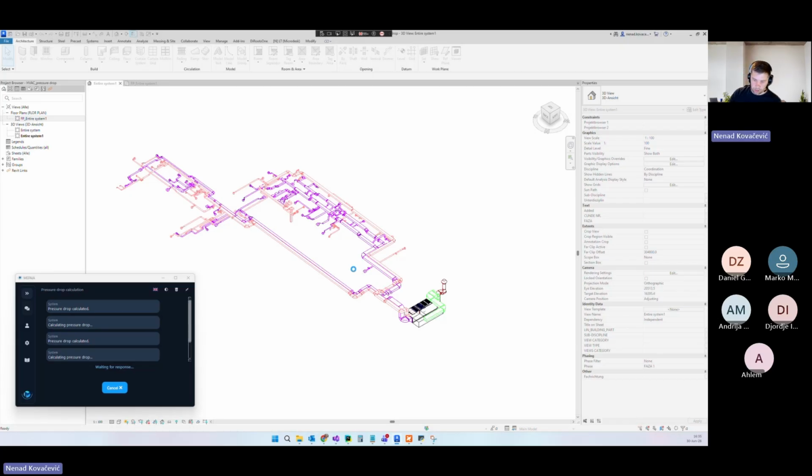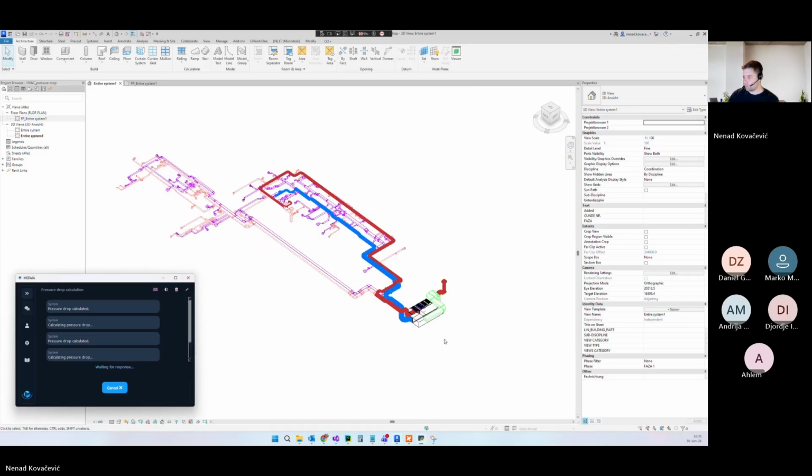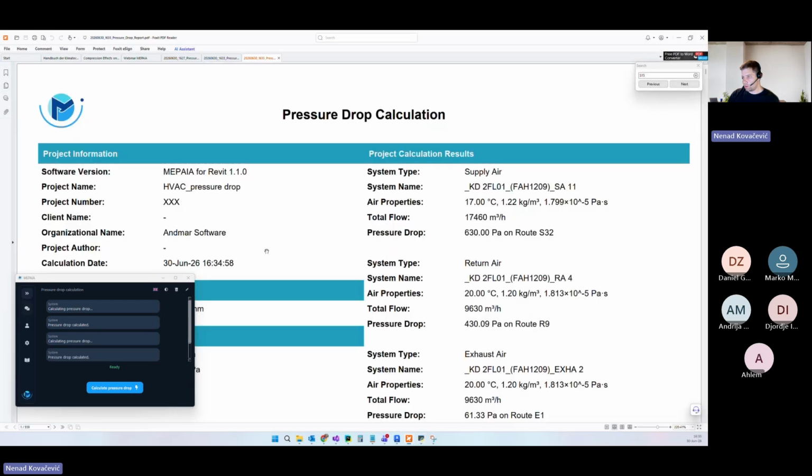And the other option is, as we did previously, when there is a shared network for fresh air, you can just set, I have a plenum box. From here, I'm calculating that I have 50 pascals, and the calculation will start from the selected element. I will also show that, just for this one to finish. Okay. So fresh air, it's not in any color.